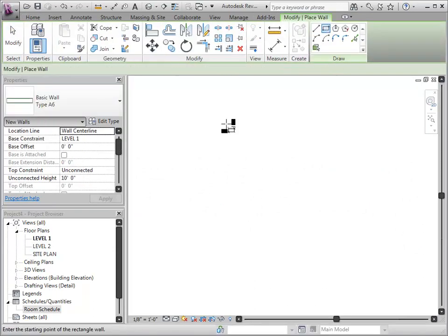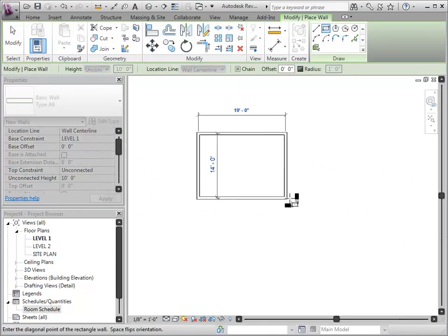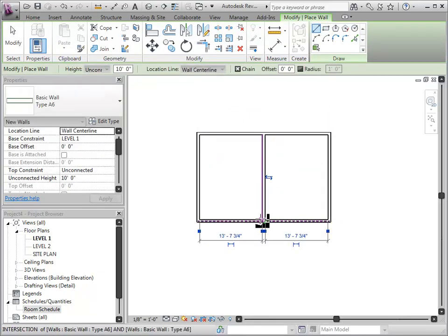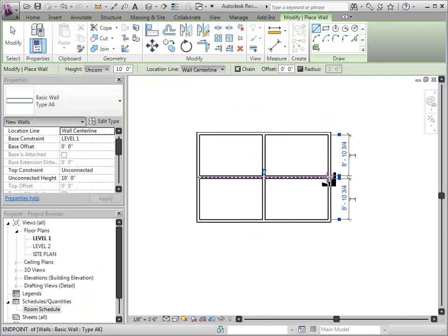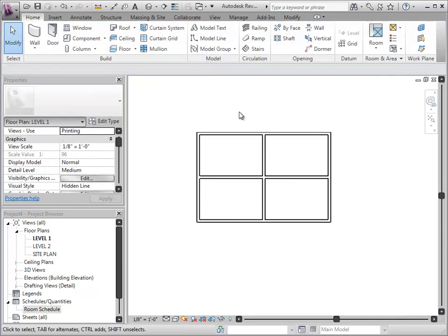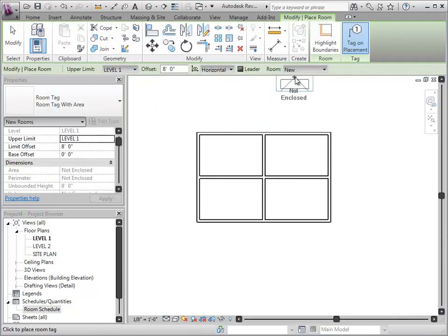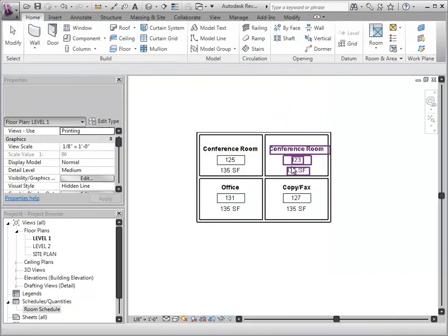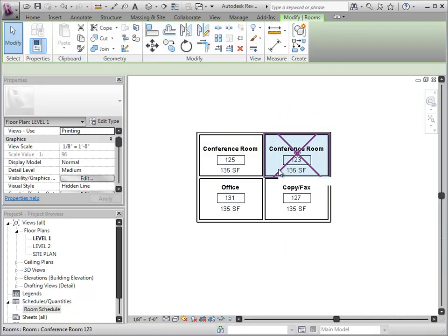Now, a room layout design can be done in Revit. The enclosed areas can be created using walls or room separation lines or a combination of the two. Once the design is complete, select the newly created rooms from a pull-down list and place them within the enclosed areas. Under the properties of a room, any parameters that are mapped will automatically be filled in for scheduling purposes.